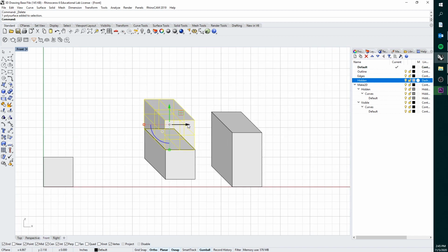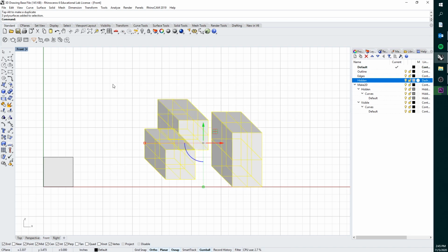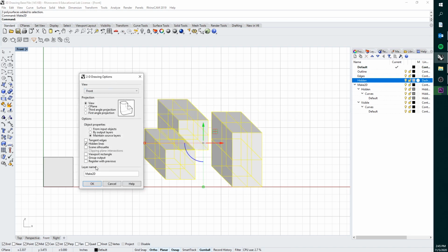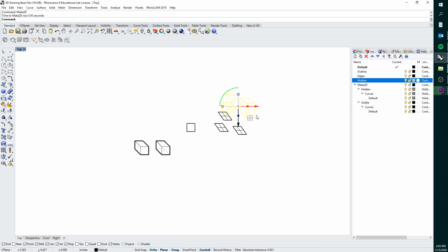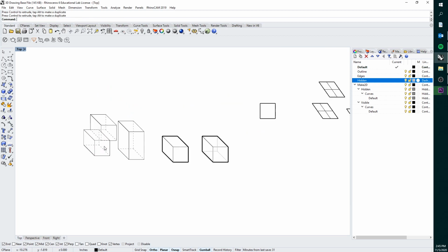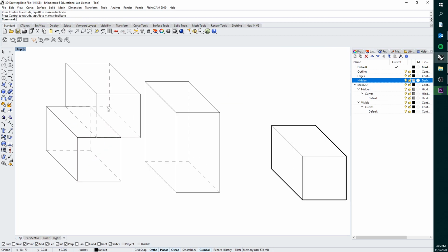Now this looks a little bit weird. You guys wouldn't do this, but I'm just going to move this for the sake of doing the drawing. Then we can do a make 2D. Click OK. And again, I went over some of the line weighting techniques that you might want to use. I'm not going to go over those here. Those are in the last one, the AXO one.